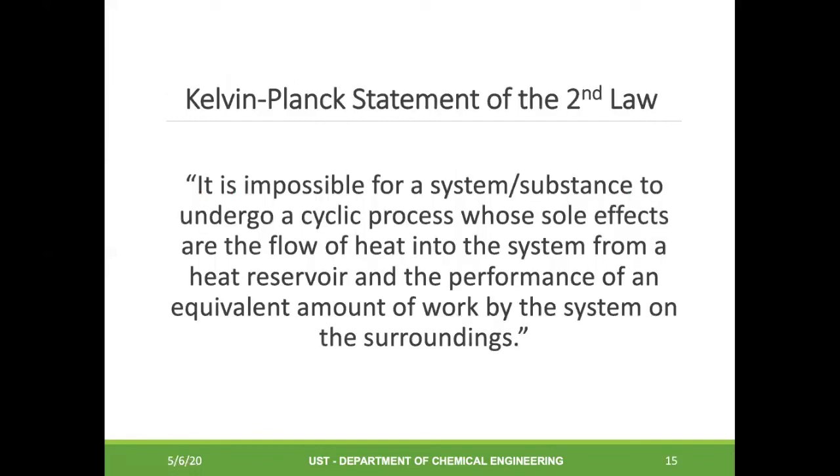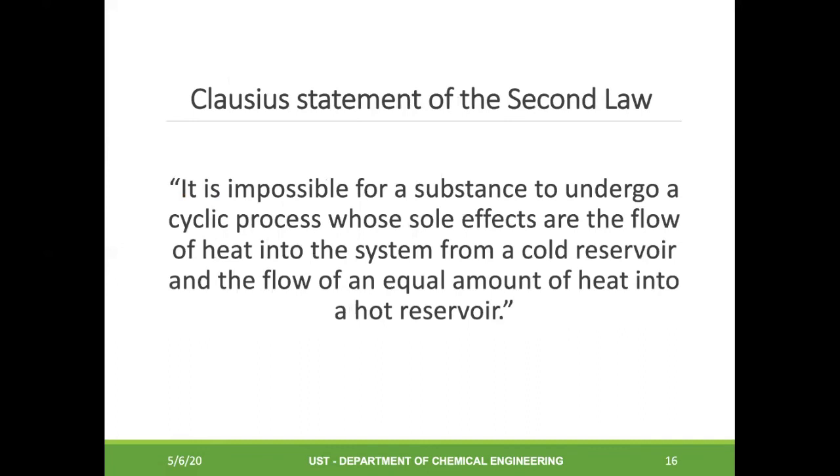Another statement of the second law of thermodynamics is given by Kelvin-Planck. It is impossible for a system to undergo a cyclic process whose sole effects are the flow of heat into the system from a heat reservoir and the performance of an equivalent amount of work by the system on the surroundings. Another statement of the second law is by Clausius, which states that it is impossible for a substance to undergo a cyclic process whose sole effects are the flow of heat into the system from a cold reservoir and the flow of an equal amount of heat into a hot reservoir.